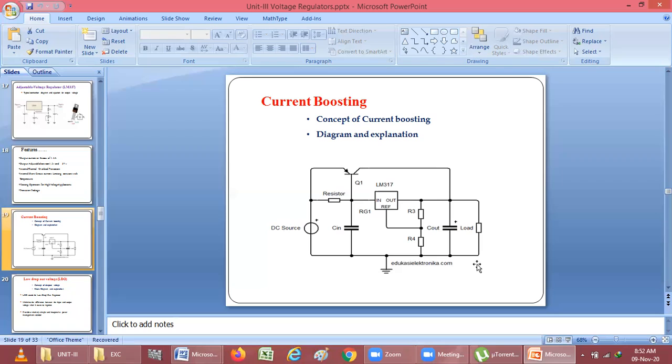Again, if you see, a voltage regulator is a simple device with a simple feed forward design. And if you see the circuit diagram for the voltage regulator, we are using an amplifier there. So here we can say a voltage regulator is a device which uses a negative feedback control loop. It uses a negative feedback loop because we have seen there are two types of feedback, positive and negative. An oscillator uses positive feedback and an amplifier uses negative feedback, and in the voltage regulator we are using the amplifier. So we can say the voltage regulator will use a negative feedback control loop.